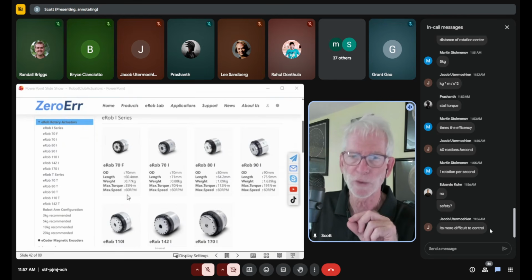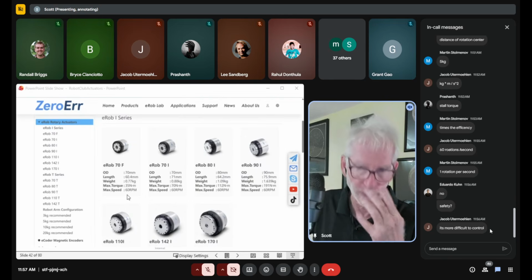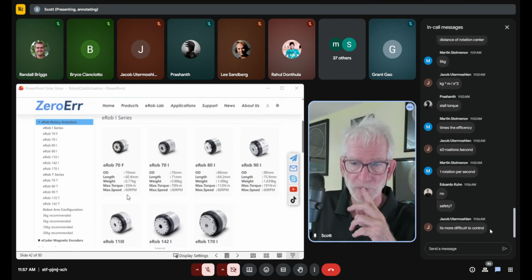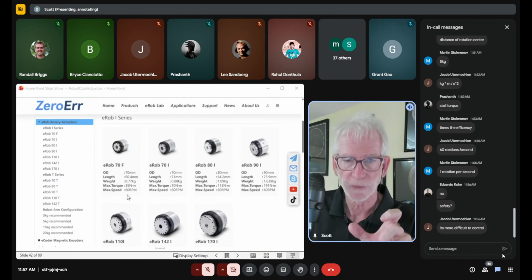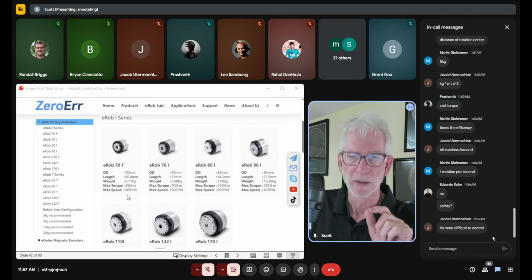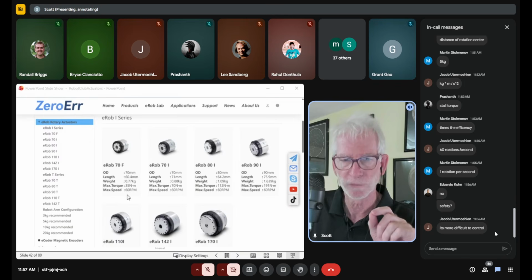Now, these motors are torque rated. They're not necessarily acceleration rated, but they're related, of course. It's going to depend upon the mass that's there. So if you want to hit 60 RPM over a range of 180 degrees, your acceleration at a minimum has to be 120 RPM per minute, basically a factor of 2. If you do it in degrees, which is usually what I'm thinking of, if it's 360 degrees per second, your acceleration has to be 720 degrees per second squared. And that means right at 90 degrees, you will just hit your peak. At that point, you have to hit your brakes and slow down.